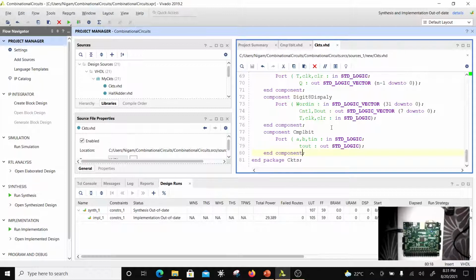In VHDL I've seen people doing this. That's not the right way of doing it according to me, because you should be closer to hardware. You should not just say count equal to count plus 1. That's a C concept, a higher level language concept. You are programming in VHDL, so you don't know what Vivado is going to do. Is it going to give you a very optimized output? I don't know, so I don't want to take that chance. That's why I'm teaching you how to do the logic.